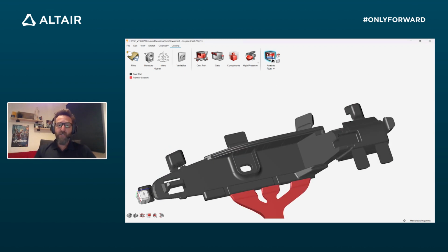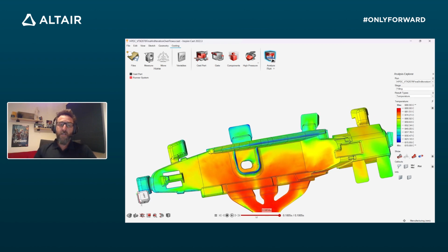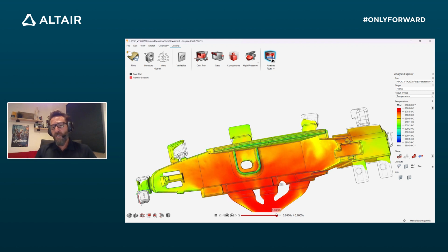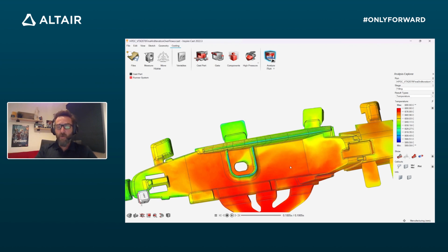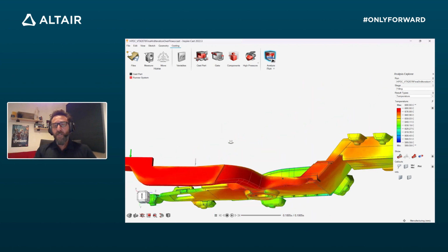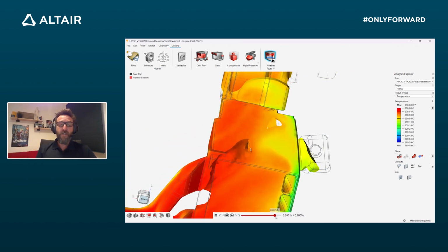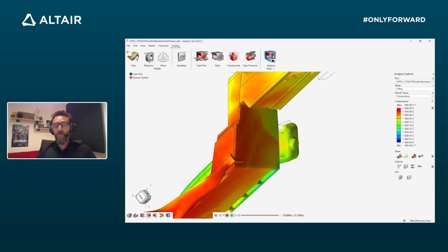Once we have modified the overflow, let's run a new iteration. Remember, we already ran 5 iterations. In each iteration, I implement some changes, and now you will see the material flow tends to move the air to the new overflow position. The advantage of simulating during the design is that we can improve the design based on the information we get from the simulation.